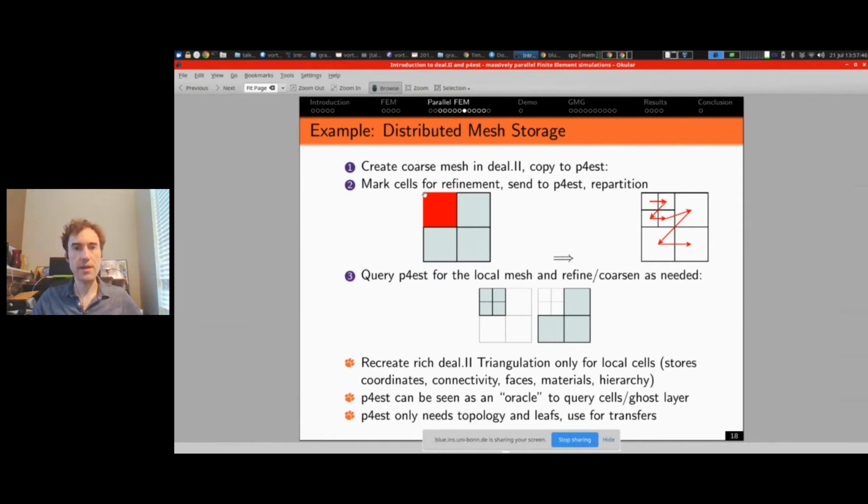So for example, I start just with my coarse mesh. Maybe it's the red cell, right? And then I ask p4est, is this within my area? p4est says maybe yes. And then I ask p4est, well, is this actually a quadrant in my domain? p4est says, no, you have to refine. The quadrants are finer. And then I know that I have to refine, so I call into deal.II to do the adaptive refinement. I split the cell into 4 children, and that does the correct thing with positioning the vertices and the connectivity, etc. And then I ask p4est again, hey, I have these 4 cells. Do I own any of these? And if yes, I mark them as owned by me. And if not, I'm going to continue.